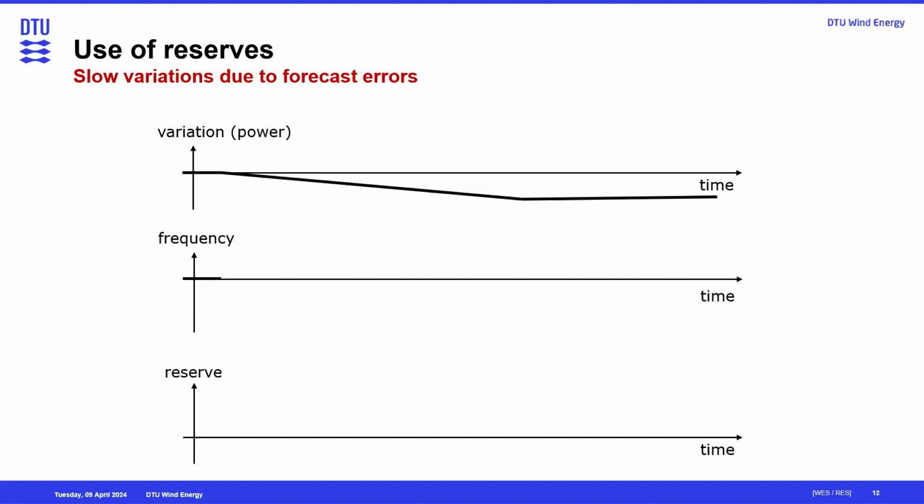Okay. So what is the frequency? It's a very basic concept in any AC power system. Like you say, it's the number of cycles of the AC current, of course, but it's also the synchronous electrical speed at which all the synchronous machines in the power system are rotating. So in order to maintain the security or stability in a power system, we would like to contain the frequency within a very strict band, and that's the quality of frequency or the quality of the power system.